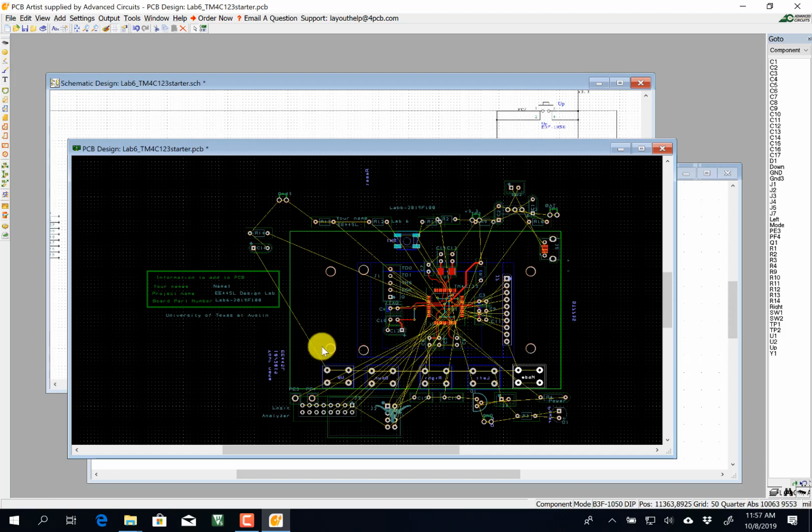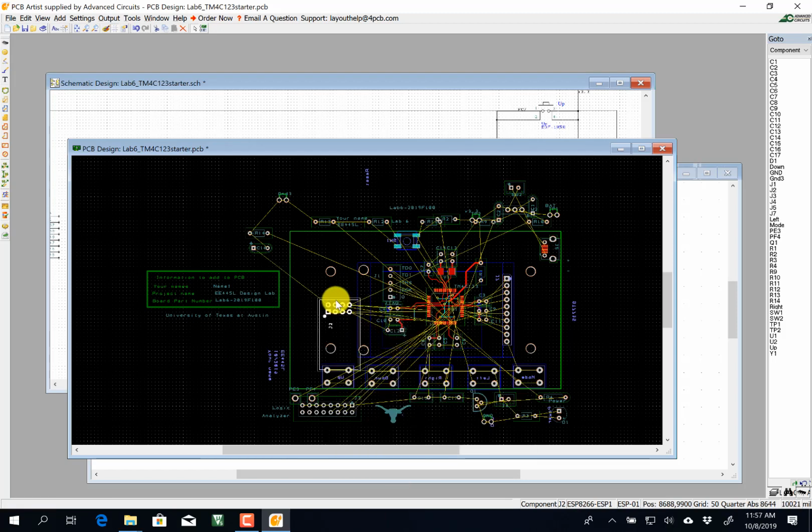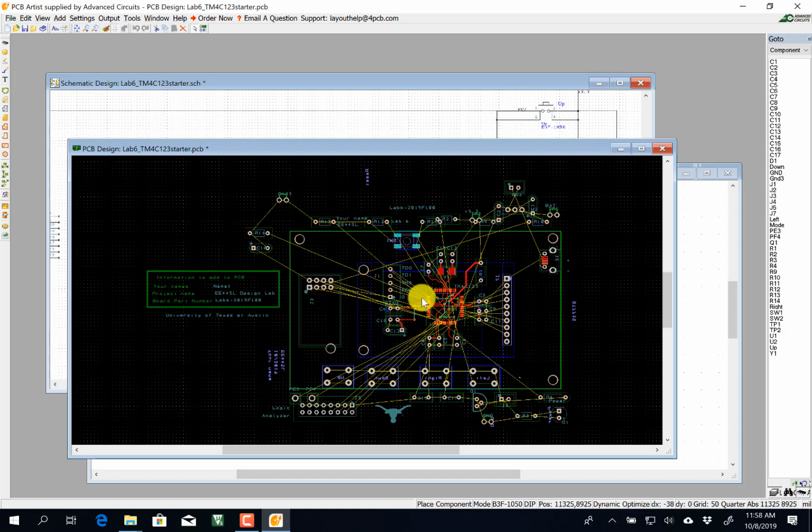All right. I want to place things around so they fit. Okay. Where's my ESP? That's a weird one. My ESP, I'm going to put not on the same side as the display, but on the same side as the processor. So I'm going to move it approximately here. I'm going to move my drill holes into the center. This is my power connector, which has got to face outward. These are going to be my drill holes for the board. One more. All right. Let's see.